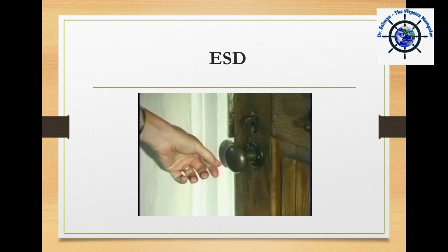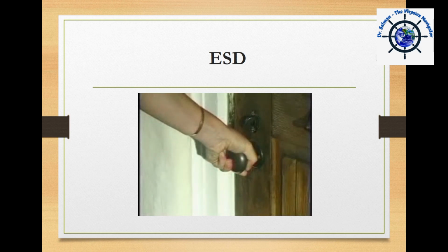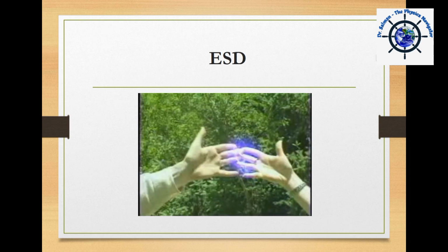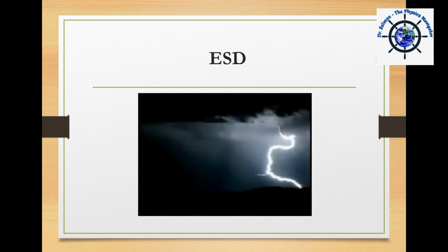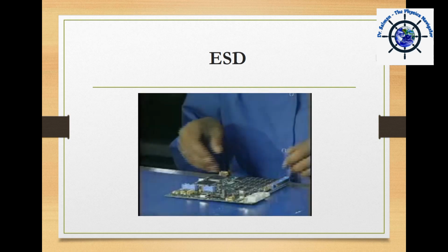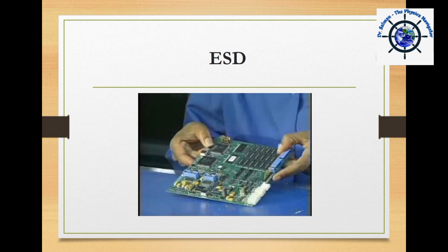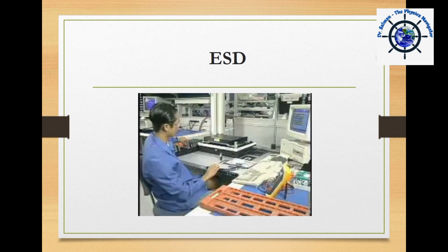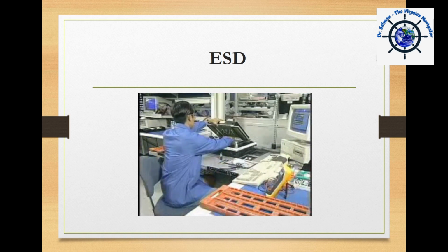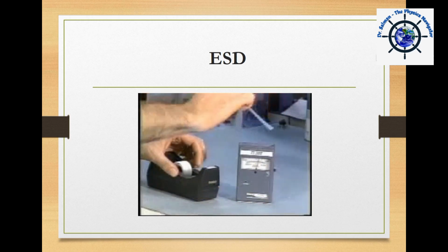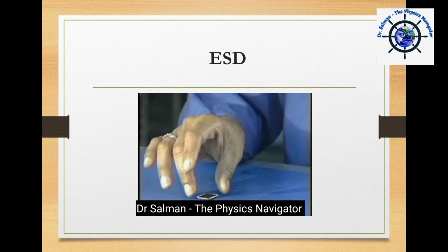These examples of ESD, which we can see and feel, last for a fraction of a second and contain anywhere from about 2,000 volts, the lowest level most people can feel, to over 25,000 volts. However, below 2,000 volts, there is still enough static electricity to cause static discharge and damage electronic circuits, even when we don't feel it. Still, we're generating ESD all the time, and a lot of common objects around us can be sources of static electricity too.